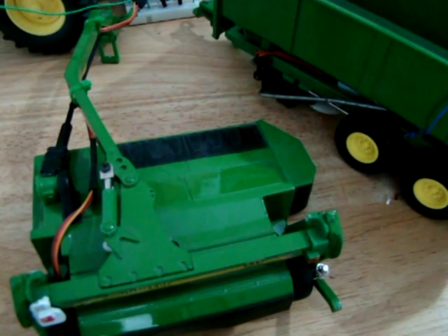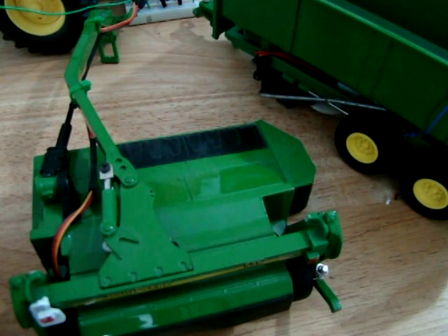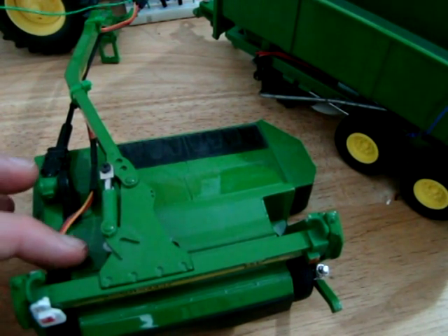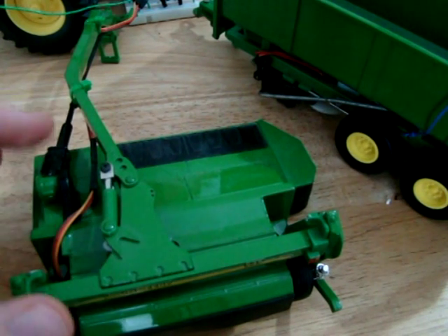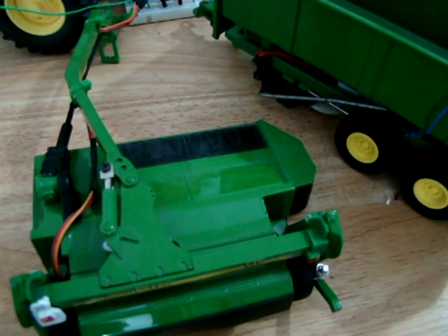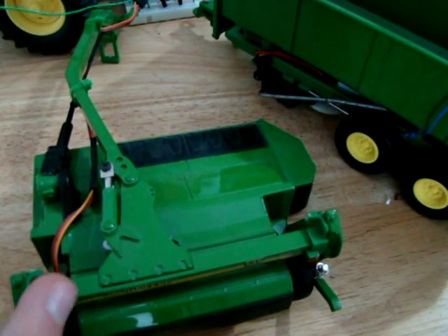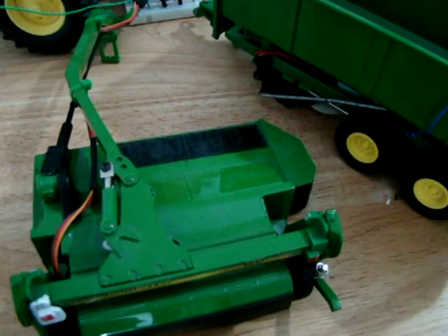Okay, so I have the external device set up. This is my mower, which basically just has a servo in it, and the servo steers the mower. So the command for the external servo is 03, and I happen to know that the servo in this mower operates between a value of 25 and a value of 50.